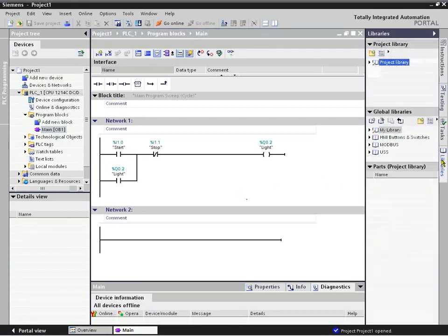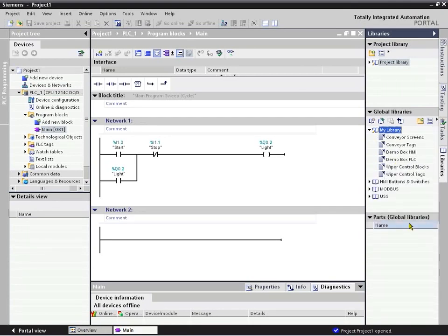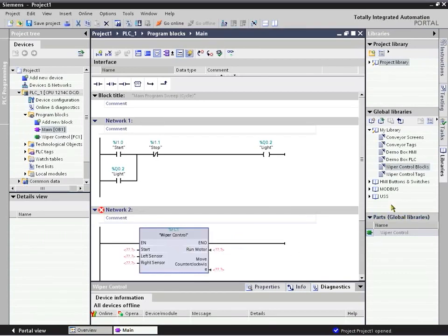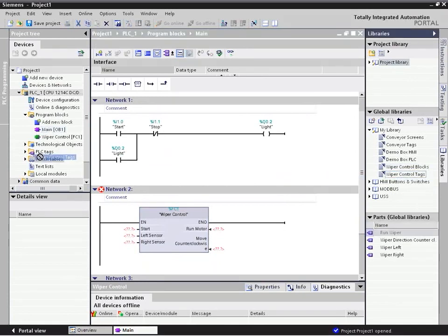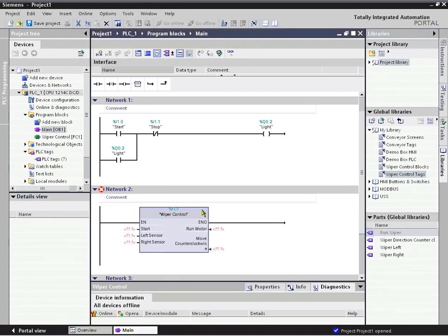We can go right over here to our libraries tab, and I've already pre-configured a library folder that has several portions of reusable code that someone quite often uses for their machine, their control, or their systems. The idea is that we can simply drag in these blocks that are already proven, already tested logic, into any existing or new project, then bring over their tags into the tag database for this project, and simply parameterize this particular block. And this saves a lot of repeat programming.